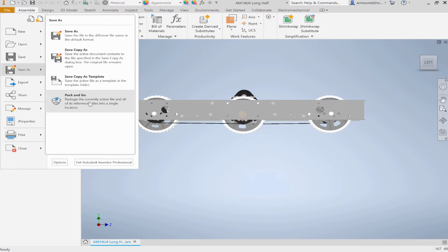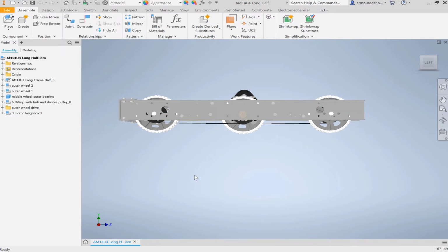And speaking of that, make sure you don't move your files around unless you're very careful about it and adjusting as you do it, because then the same thing happens. The files aren't where the assembly expects them to be, and it freaks out and you have to show it where they are, and that's just generally a pain.